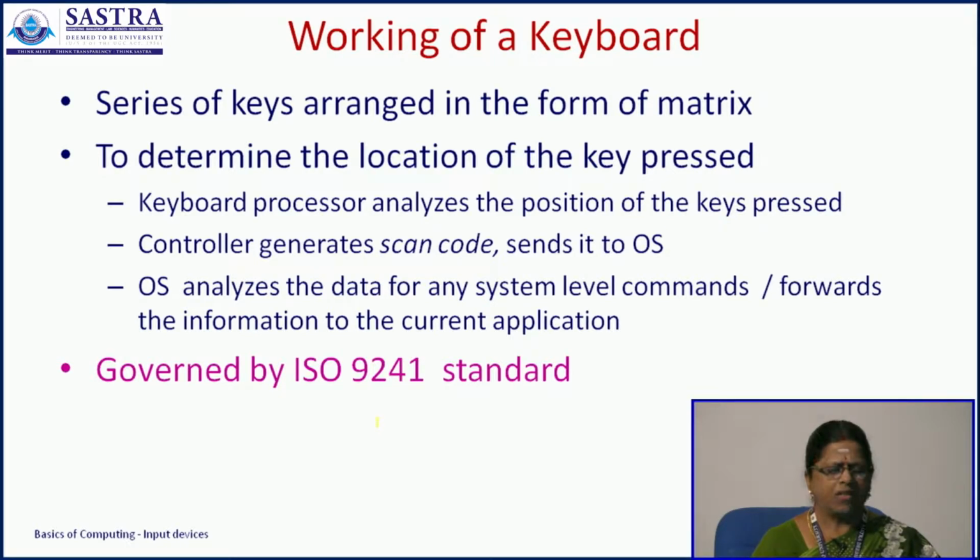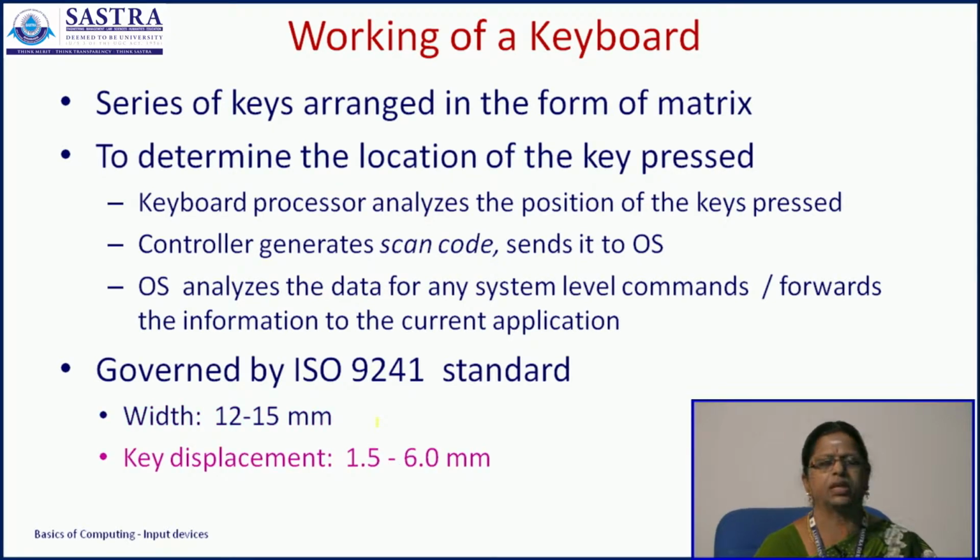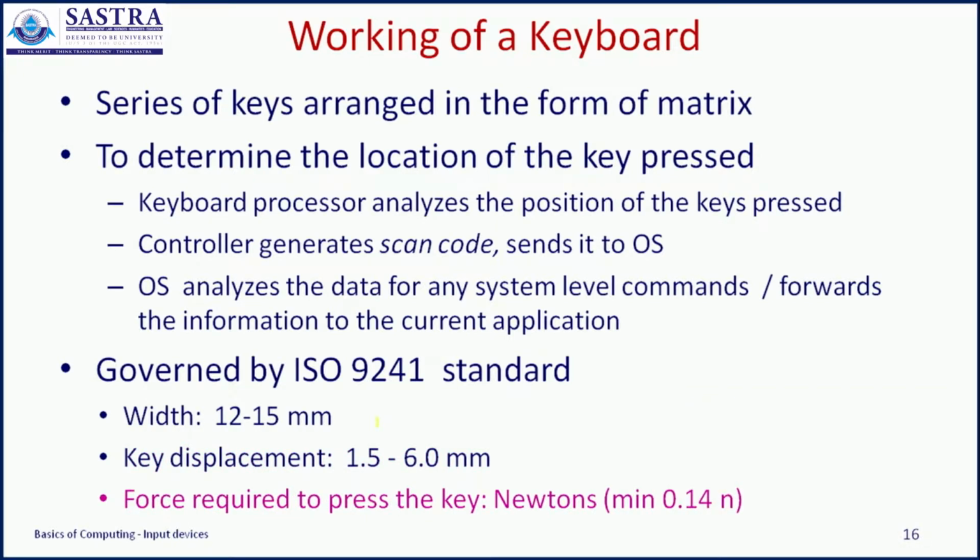It is also governed by a standard which is the ISO 9241 standard. It means the width of the keys can be 12 to 15 mm, the key displacement can be from 1.5 to 6 mm, and the force required to press a key is measured in newtons, which is a minimum of 0.14 newtons.